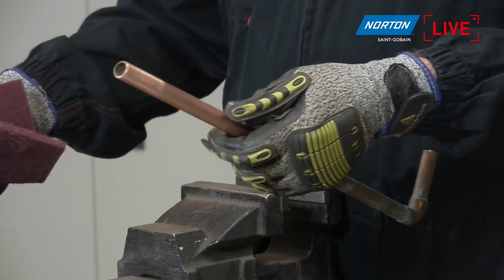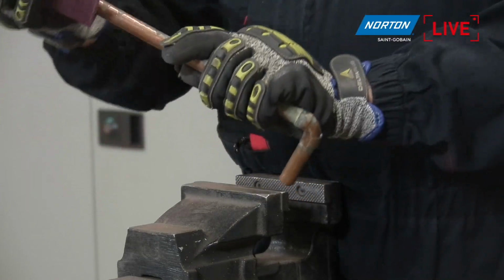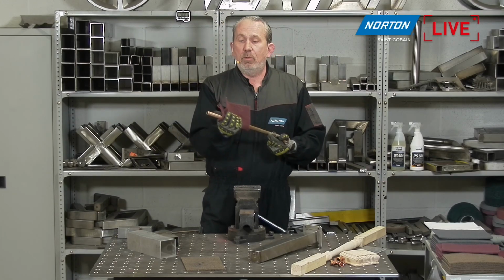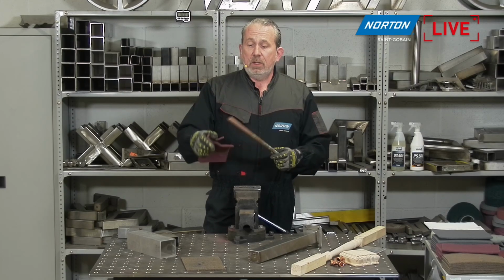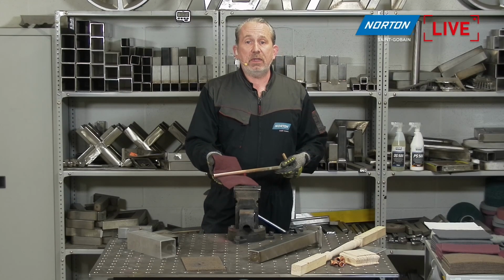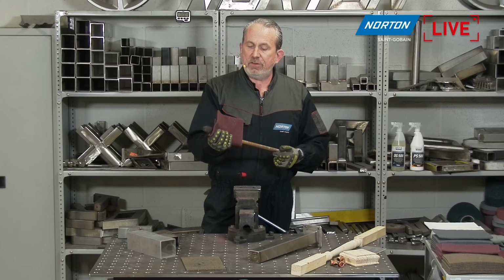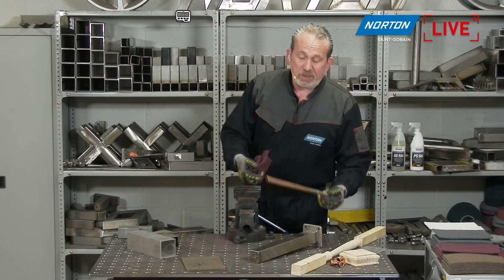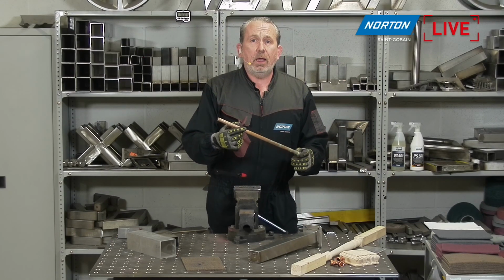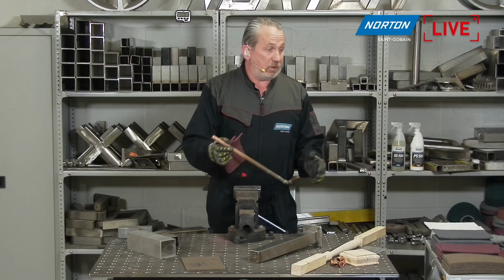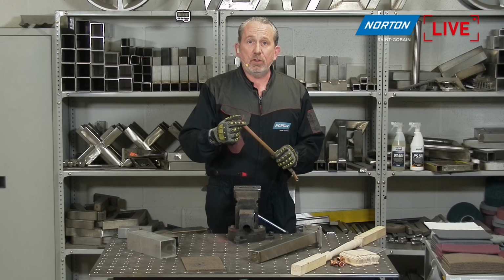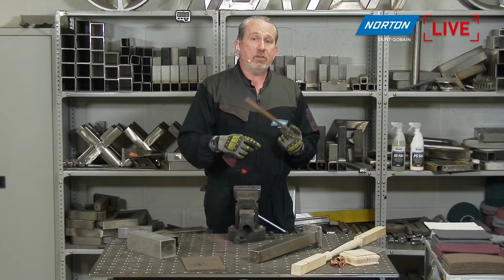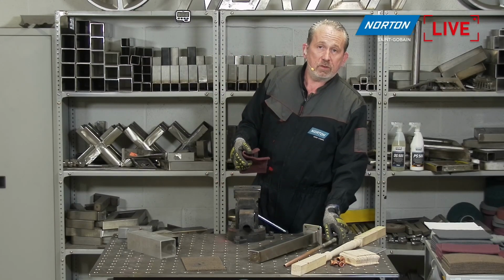So again, really quickly to finish that, and you see a lot of applications where people actually have copper pipe on show these days rather than burying them in the wall. And sometimes it doesn't look so nice, but you can see this finish you get from this hand pad is ultra bright and ultra smart. So you can finish anything like that very quickly. So easy, especially on materials like copper. It's soft, again, comparatively, and we don't want to damage that material by using an abrasive paper. It would dig into it too much, so we need a nice uniform finish on there to make it look good and ensure that it gets a good seal with the soldered joint on there as well.